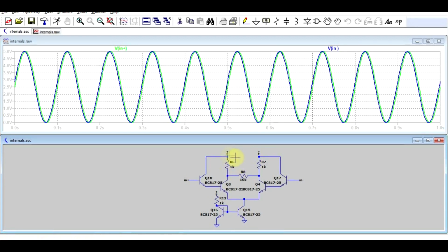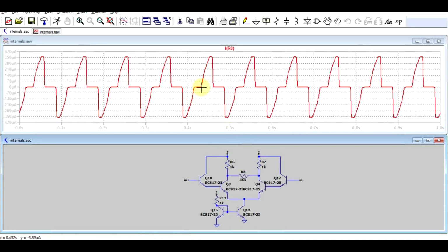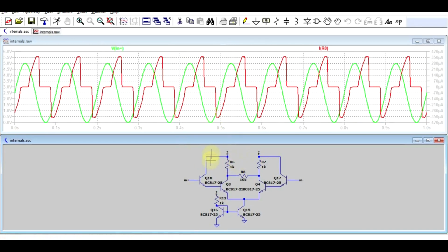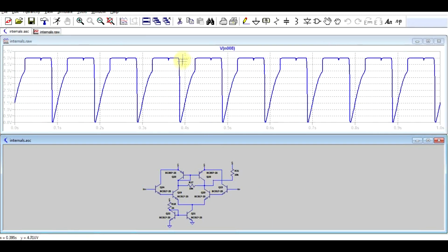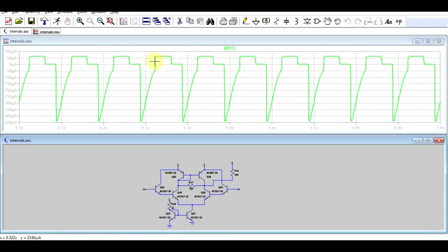That means that this time we have a whole volt to spare on our high side input stage. Therefore we can ensure much higher currents through these resistors. And the circuit will work a bit better. So we still have this problem, the current flattening out when the input voltages are very high. But again, if we replace these resistors with a current mirror, our output will be much more clear. So we will have a proper response when our input voltages are very high.